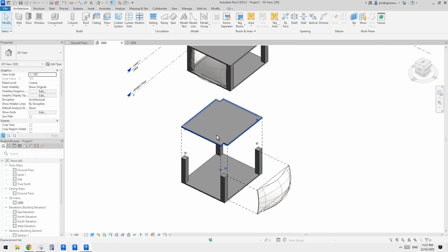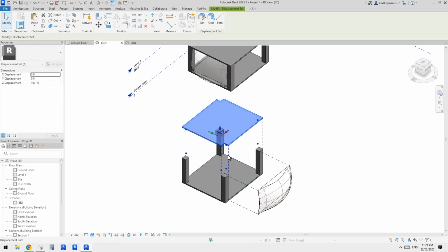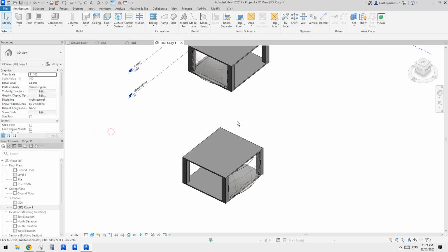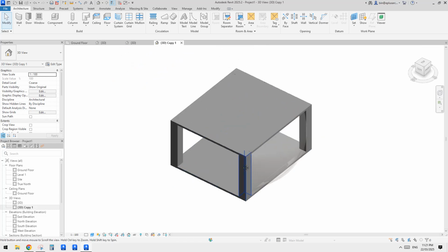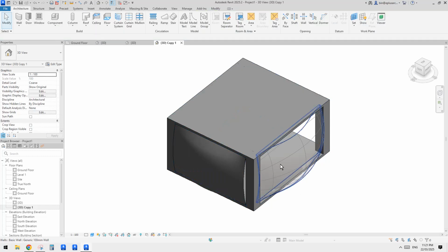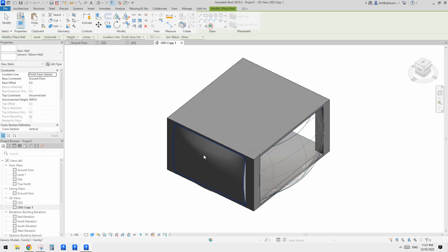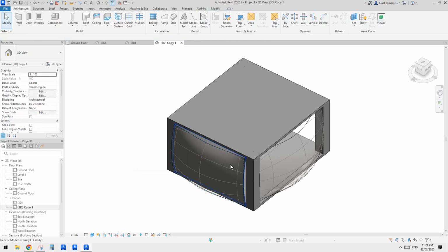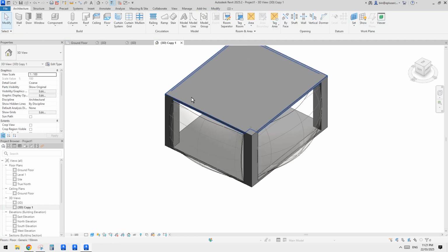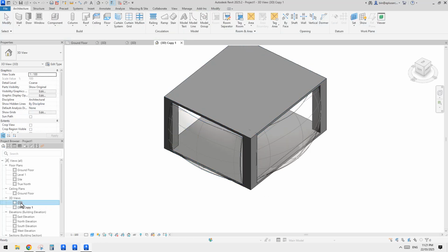and then you might want to go back. You don't want to reset everything, right? So you can just duplicate that view. If you duplicate that view, everything will go back. In this new 3D view, you can just create another one. So I'll just quickly do it. Doesn't matter, just do it from to the edge. Okay, so don't ignore the gap, and then create a wall, CS, pick face, pick wall. That's it, and then let's select the mass. Let's demolish in the same phase, and we can just go back to the previous one.